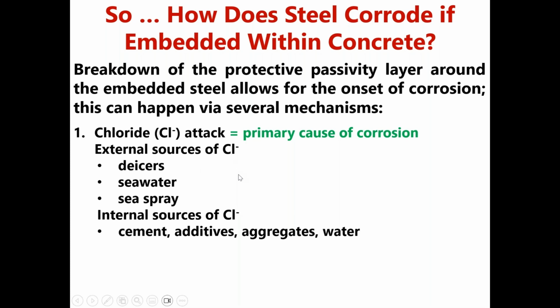Well, if we're talking about concrete that's used externally, right outside, de-icing salts, by definition, have a lot of chloride in it. Seawater has a lot of chloride in it, and also seawater, if it's sprayed on the building, not submerging the concrete necessarily, if you're spraying seawater onto concrete, that will introduce the chloride into the concrete. Understand, obviously, that concrete is porous and permeable, so water soaks into it, and moves within it fairly easily. So if there's chloride in the water, which is highly soluble, then it'll get down deep enough to where the